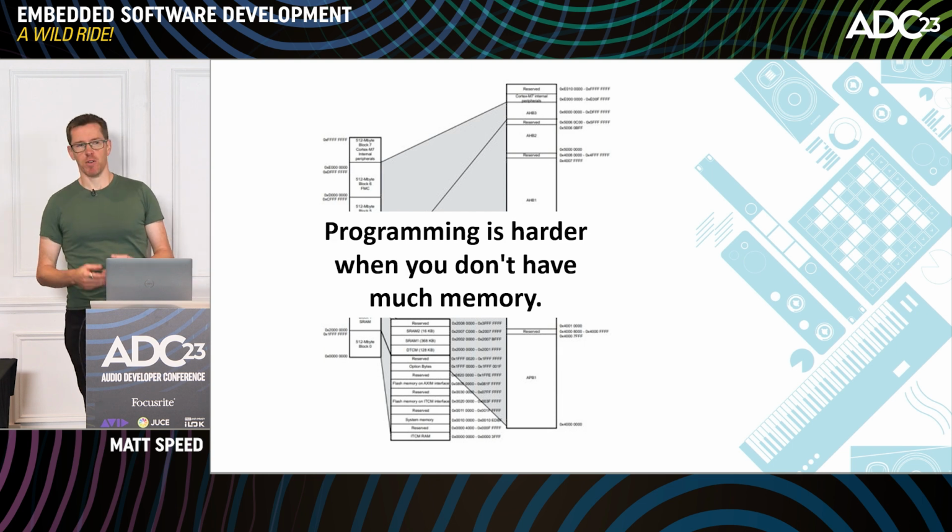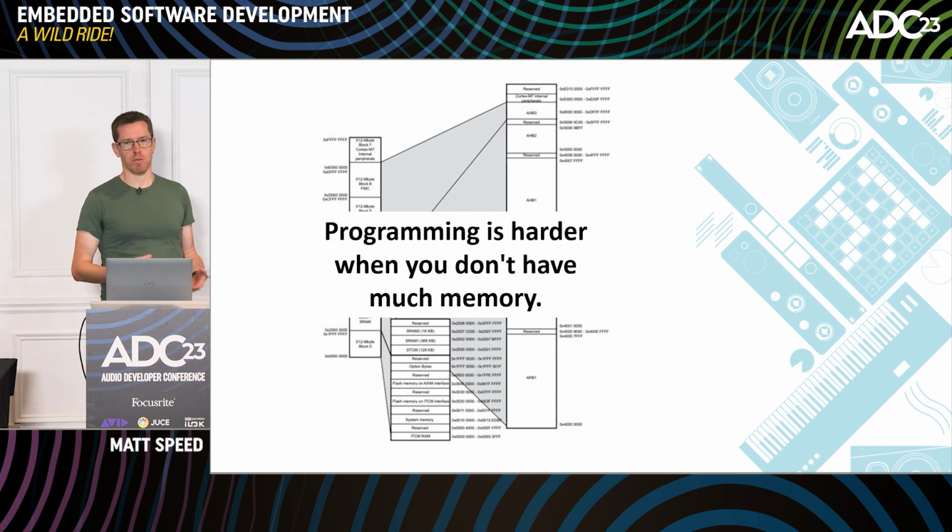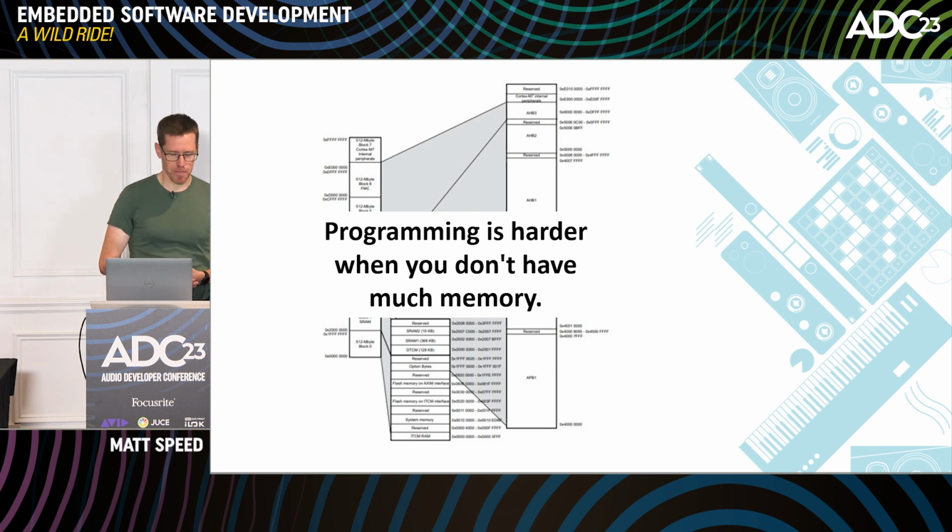Like a microprocessor, you can go off-chip if you want more. So on a desktop, you'd hook up some nice DDR4 RAM and a PCIe hard drive. It's not really possible with a microcontroller. Your RAM is probably going to be accessed over standard SDRAM. You'll have a flash memory that you might be able to access over SPI, but it's going to be a lot slower, so you're really dependent on what's on the chip, and there's not much of it.